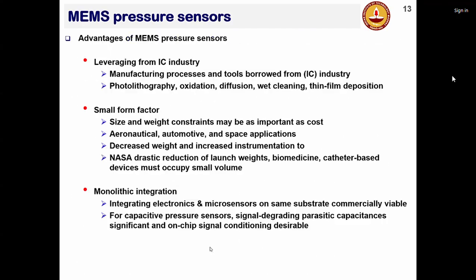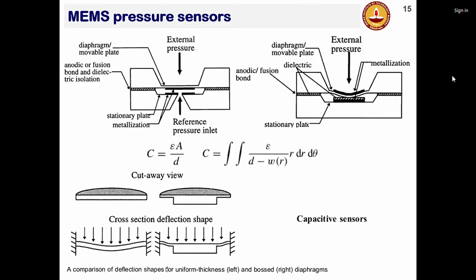okay, this is something that I have to teach you, but there is a process called photolithography, oxidation, diffusion, etching. So these processes they follow to create this kind of structure. It is not really milling or traditional machining. They do what is called clean room processing, that people in semiconductor manufacturing adopt.